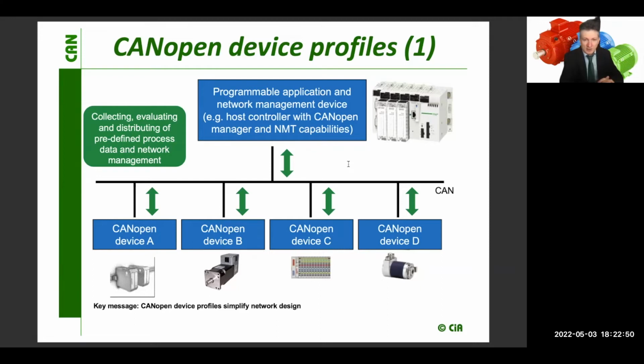So just for example, CANopen device A illustrates a sensor network, whatever it might be. It looks like I/O modules, but it is not entirely that. Device B is our drive. The motor can be attached to this, but it is drive controlled in there.